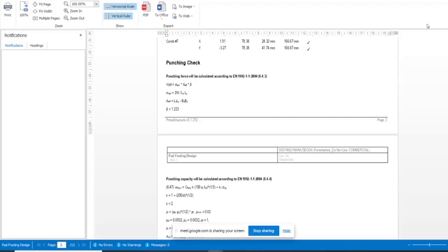For example, in flat slab, you see that at the region of your column points, they create things like column heads. The ideology is to make those points thick enough to prevent the punching through.